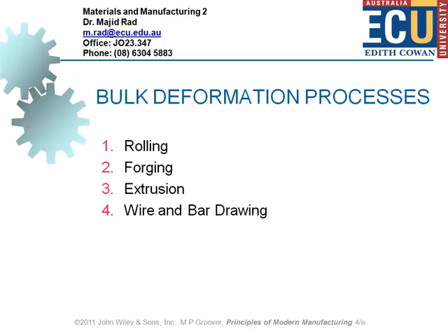Bulk deformation processes are those processes which are used in order to significantly change shape and dimension of the materials, mainly metallic materials, when there is significant change of shape, and when production quantity is relatively high, meaning that productivity in these processes is greater than that of machining processes.